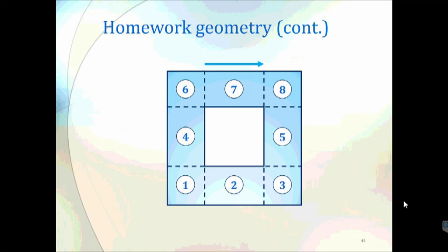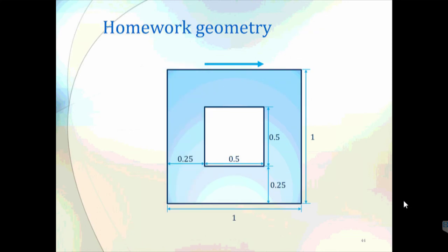So, although at first it may appear easier to just make this large block and have another block inside, the block inside will not have any flow inside it, and there is no need for any mesh inside this block because there is no flow taking place over here. So we have to identify the node points where flow will be taking place,